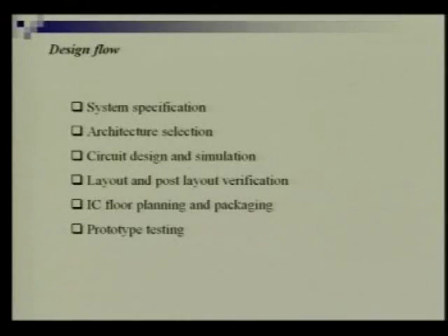Otherwise, there is a term in VLSI, they call it correctness by construction: from the beginning till the end, people go step by step, at every level they think, then verify whether their thinking process is all right, then they go to the next step. So first is the architecture selection, then goes the circuit design. You have to do the design, and you can see that each step is accompanied by simulation.